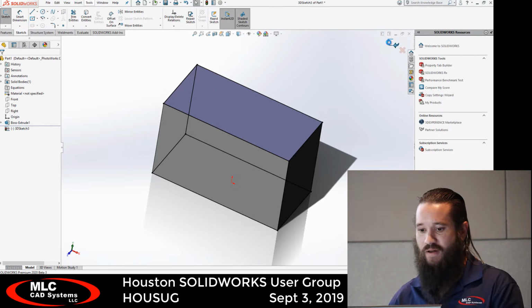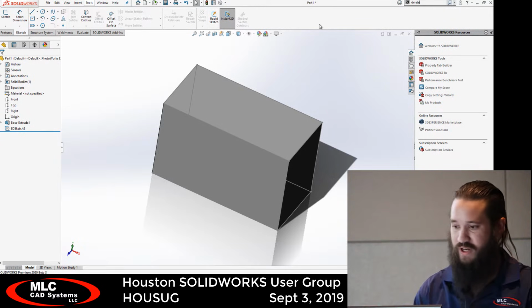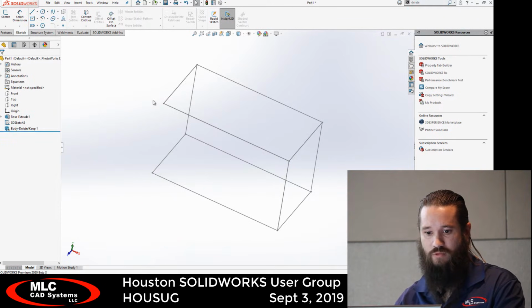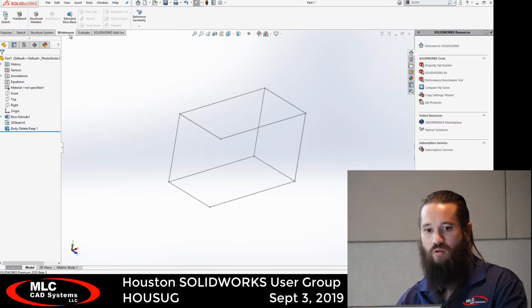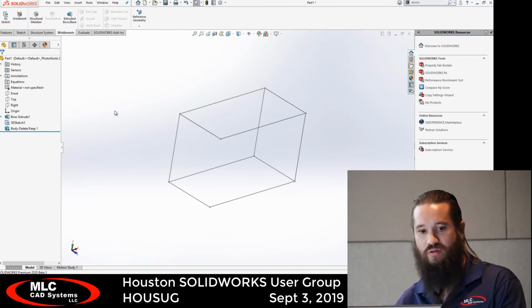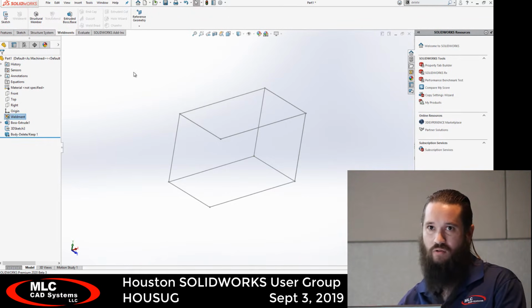Once I'm done with the 3D sketch, I don't need that solid for my weldment feature, so I'll delete that body. Oh, looks like I lost an edge. We'll play with it. So from here, we're ready to apply those structural shapes, or the profiles, at the locations where our sketch is. So I'll first tell SOLIDWORKS, hey, I'm making a weldment. It knows not to merge it. And then I'll say what structural members we want to use.